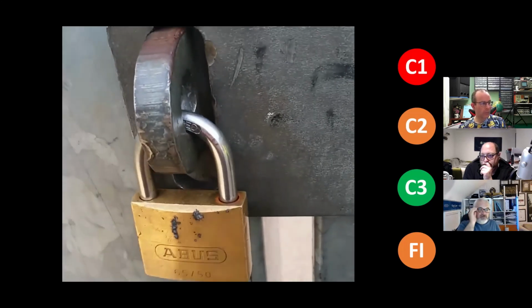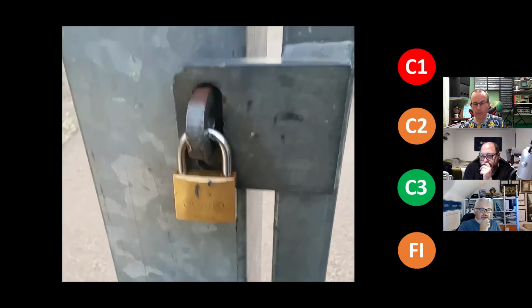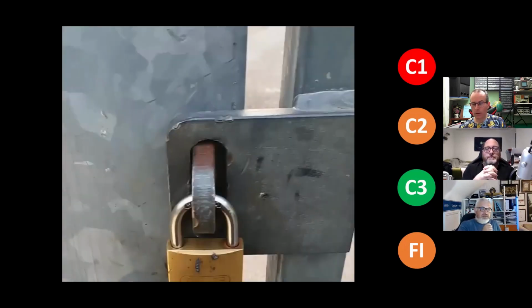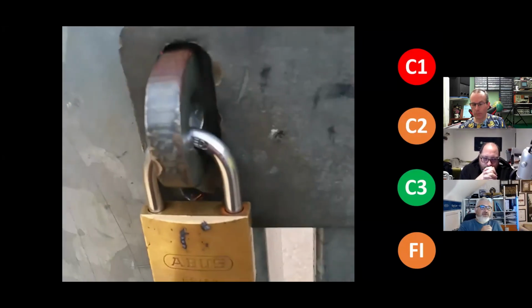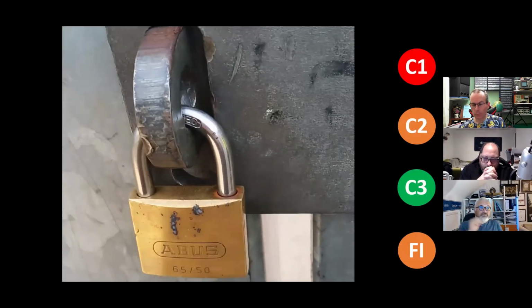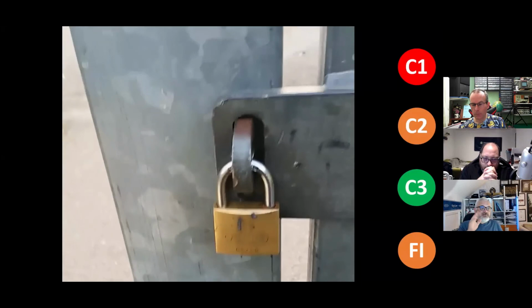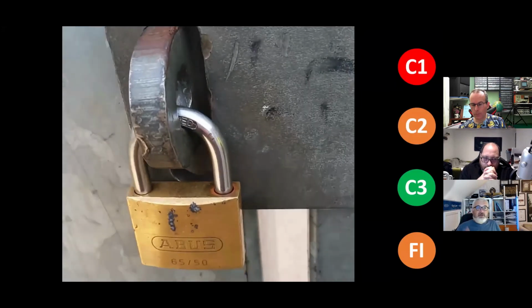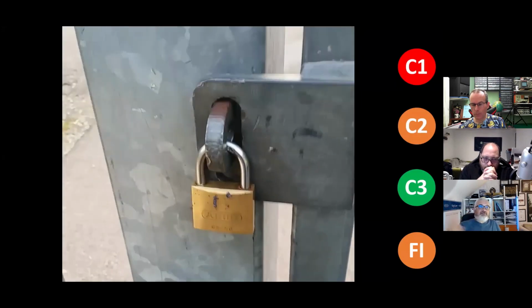You're still watching the video on the screen, but the video shows a padlock. It's a phenomenon known as tracking. This is where neutral currents will just divert to various places, and you'll see visible arcing, sparking, and that's what you see on the padlock because that's a high impedance joint. But there was sufficient energy and voltage pushing that across.